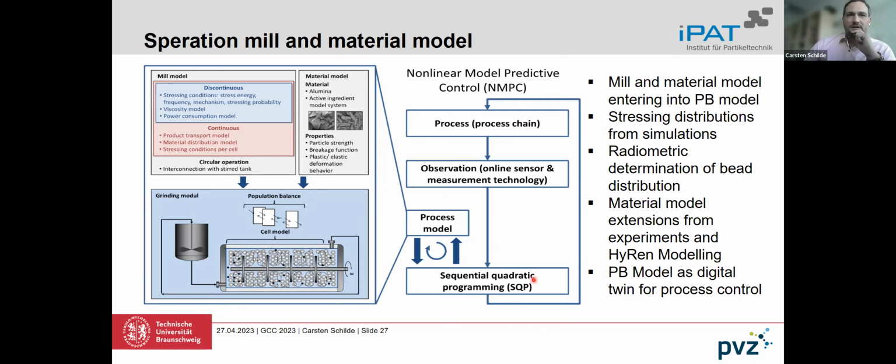You put in the population balance model, you make predictions of the particle size distributions in the future for different settings, and depending on the difference between the target product values and the actual values, you get different process control. This is the traditional nonlinear model predictive control, which has come up in the last years. We are still working on that. I cannot show results up to now. But this is one thing to do, and to control how the whole particle size distribution evolves.